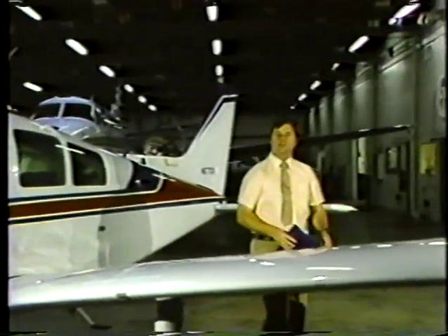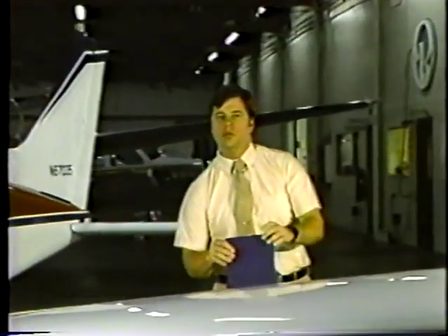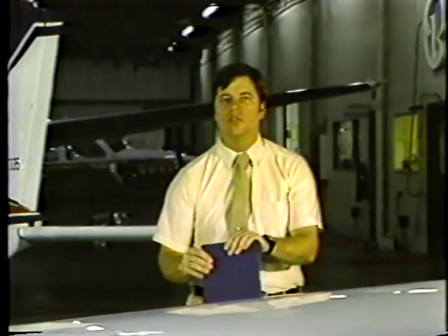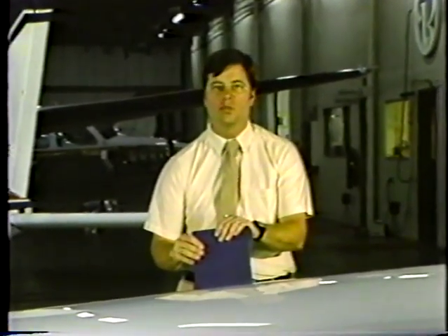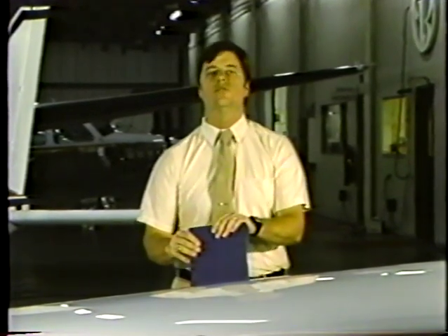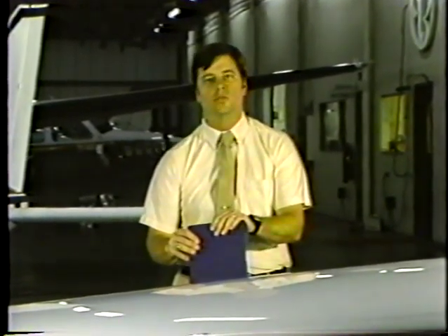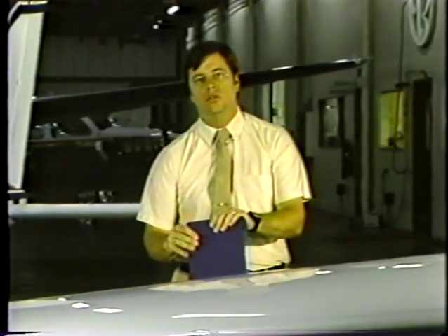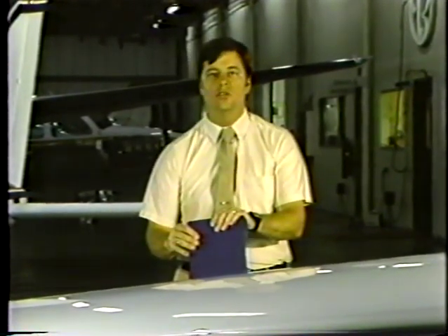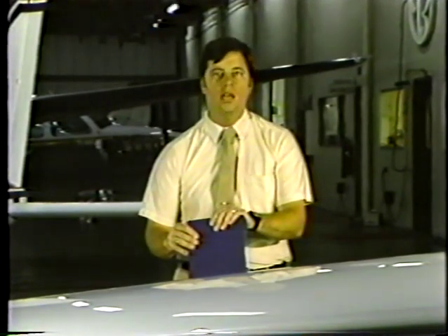The computation method appears to be the most complex of the three because of the amount of arithmetic involved. But these computations are the basis of the pilot's operating handbook tables and graphs. Let's assume a four-place airplane that has a maximum gross weight for takeoff of 2,450 pounds. First step is to make a list of everything you intend to load aboard the airplane and note its actual